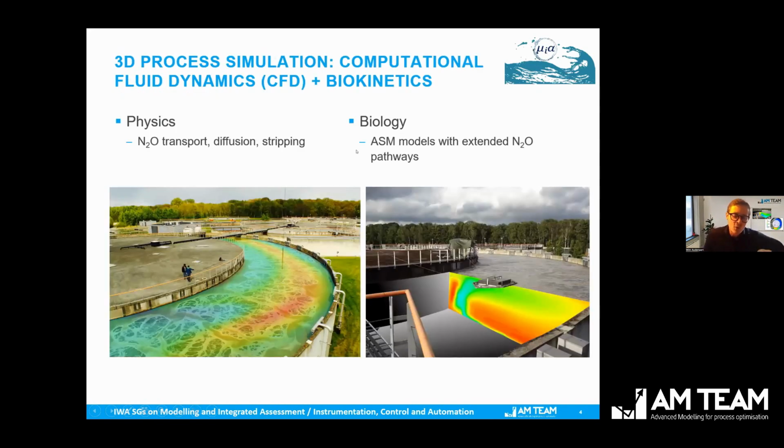So when you look at the tool we have been developing, it is a combination of a CFD model, which is a computational fluid dynamics model. It's a 3D simulation of the flow in a bioreactor. And we combine it with the biokinetics. So it has a physical part in it. This means the transport of your N2O, the diffusion, stripping, it's all included there. And then, of course, it has the biological part in it, which are the different pathways of N2O.